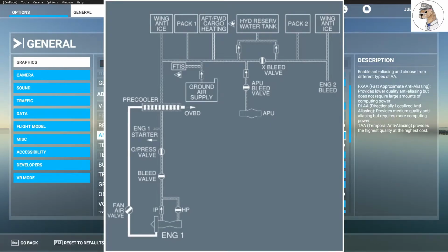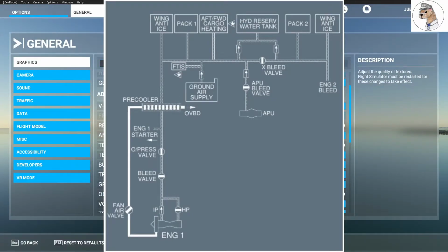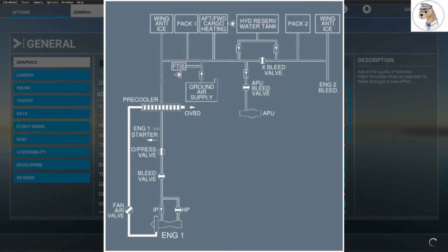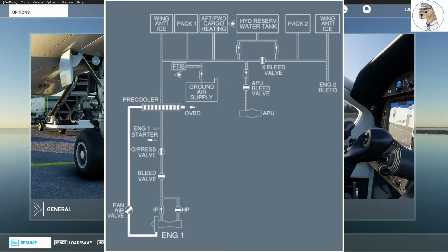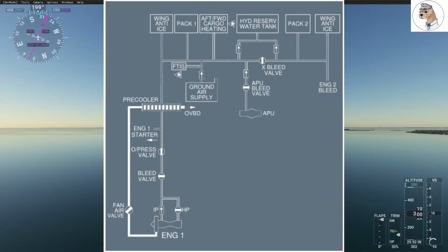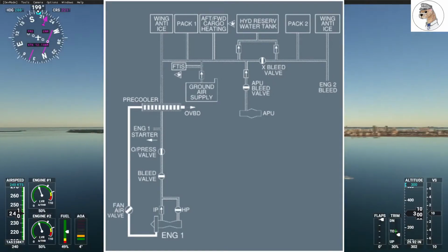It's also done electrically if we push the bleed push button switch on the overhead panel, the engine fire push button, or if the bleed air monitoring computer detects an over temperature, over pressure, some leak, maybe the starter valve is stuck open, if the engine shuts down automatically, APU bleed being selected on, or if there's no need for any bleed, or finally if the bleed temperature is lost.